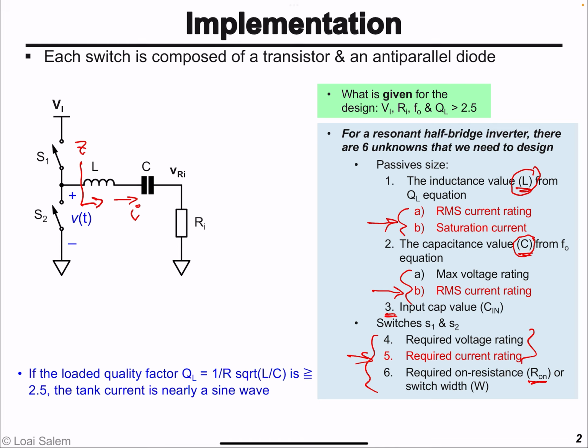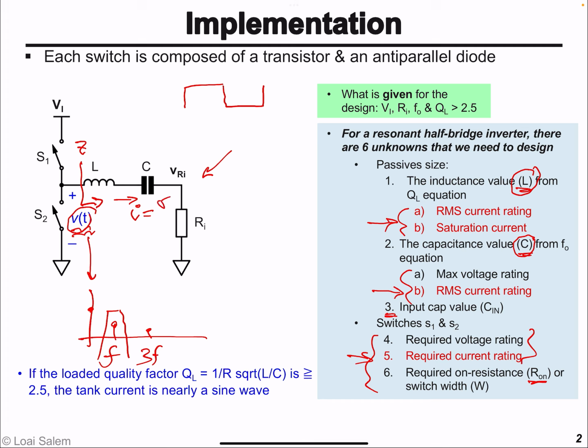RLC circuit. And we know that the voltage provided by the half bridge is a square voltage, so it will consist of a DC component, a fundamental, and a third order harmonic. And since the RLC circuit is basically a bandpass filter with high quality, it will only select the fundamental component and reject the remaining components. And so the current in the series resonant circuit will be the fundamental component of this square voltage, V1, divided by the equivalent input impedance, Z.